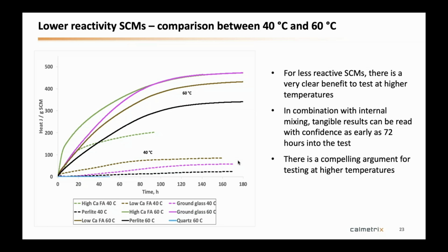So we got rid of the temperature gradient, and that's great. But there's still an overlap because you have the heat of dissolution of the salts in there. So that's something that I don't know how you would strip out. So when you see that first peak, it's the aluminate reaction combined with the heat of dissolution of those salts. So it's still not perfect if you want to see the aluminates only. You would also have the mixing energy, but generally the mixing energy is lower than these other two. So it would not really make a difference, and it's more consistent from one mix to another. So you still have that overlap, but you can capture the actual heat release from time zero completely.